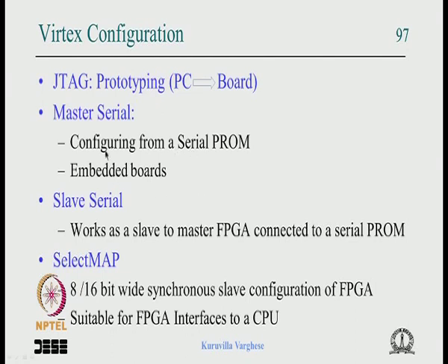And this is very useful for deploying an FPGA based embedded board in the field, because in the field you cannot insist that people program the FPGA from a PC. So the configuration is stored in a PROM which is connected in serial mode to the FPGA. At power on, the FPGA gives the clock and programs itself.